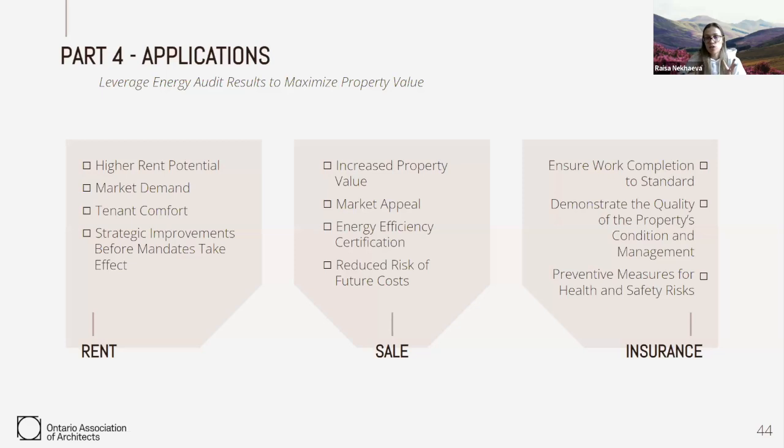They allow us to demonstrate the quality of the property's conditions and management, as well as assist with preventative measures for health and safety risk. There have been cases that we have encountered when tenants in the units have been complaining that it was always cold, and after the inspection was conducted with infrared thermography, it was revealed that prefabricated wall panels were missing insulation inside of them. Therefore, doing audits can really help ensure the construction is completed to standards and avoid potential legal issues.